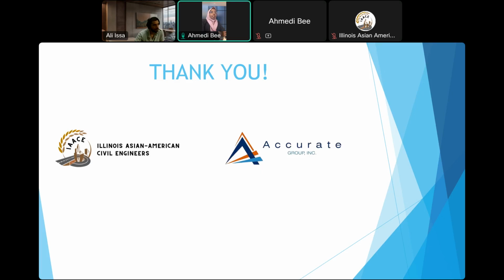That was Louis' question, actually, but I can answer part of the question, and we will share this question with Louis so he can give us information about what equipment will be better to use for quality level B. But like I said, quality level B investigation is more for horizontal positioning. It is less likely used for vertical information. The conflict study is for horizontal information only. Does that answer your question?